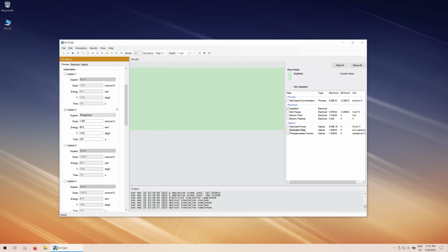And I will decrease the dose a bit more. And here, the energy. I'm going to do half a mega electron volt, which will basically create my implant much deeper into silicon. It will move it to the higher depth. And I'm going to simulate for 20 microns this time. So now let's run all the simulations together.